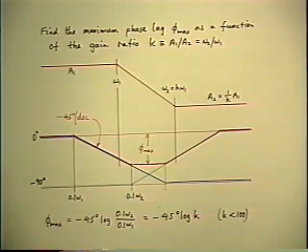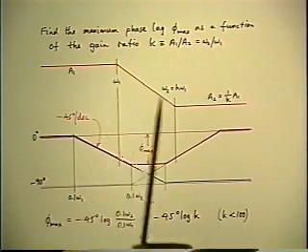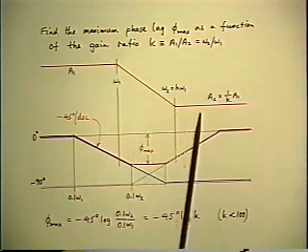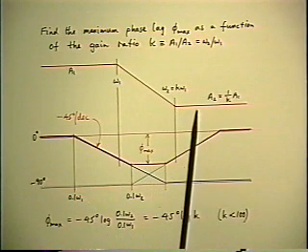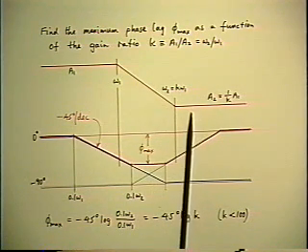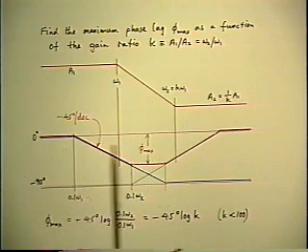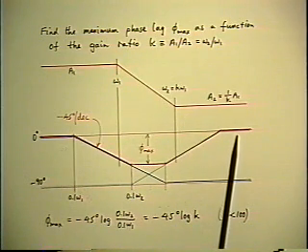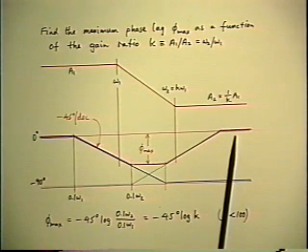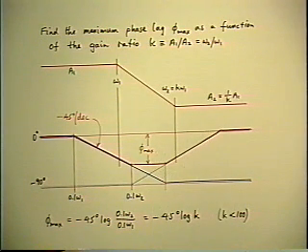The lag lead network is a very convenient way of doing that, because you see it has just the property you need. You get to throw away gain, and you've got to throw it away somewhere because it's going to go to zero at infinite frequency by itself if you don't help it. But at the same time, you don't want to stack up any additional phase lag, which would impair stability. So this network is often included for that purpose.